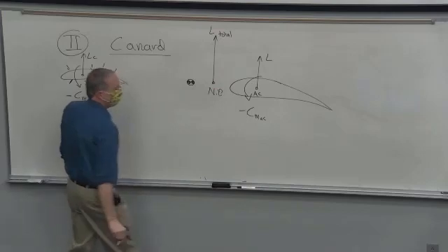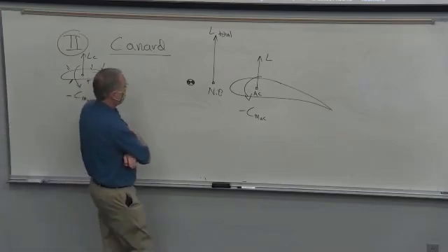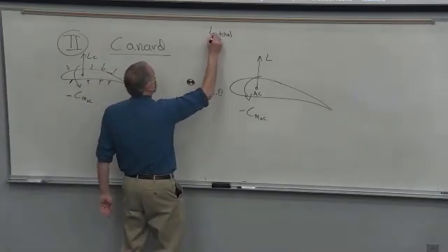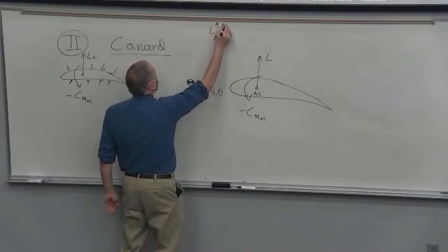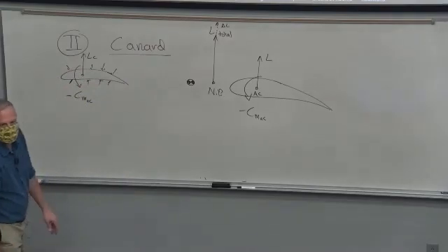And this is trickier than the horizontal tail. The horizontal tail, you just stick a tail really far back there and make it big enough. Here, you've got to balance the locations in the CG pretty carefully to get the stability here. So that when you get the gust and you get the delta lift, you get the nose down pitching moment. But it can be done.